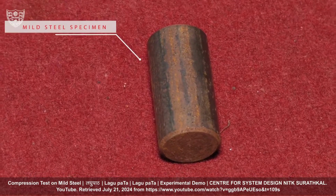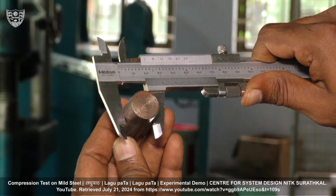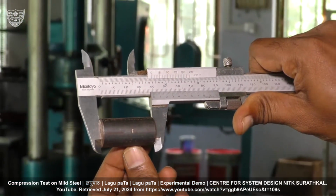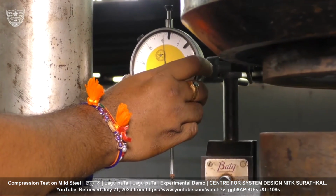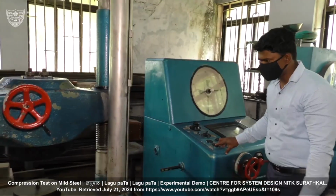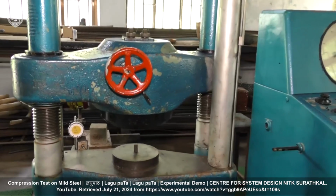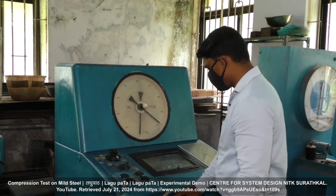So, this is a mild steel specimen used for the experiment. We measure the diameter at two places, then calculate the average diameter and the moment of inertia for the neutral axis. Then we measure the length of the specimen, and a dial gauge is inserted here so that we measure the change in length. The specimen is placed here on a platen. We relocate the cross head to just touch the specimen, and the friction determines what shape it would get, because it is a ductile material and we know that a barrel shape would be produced.